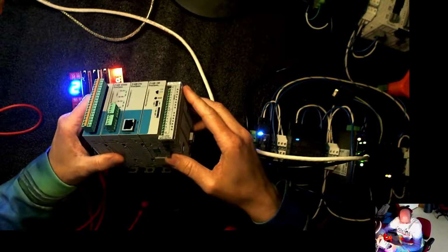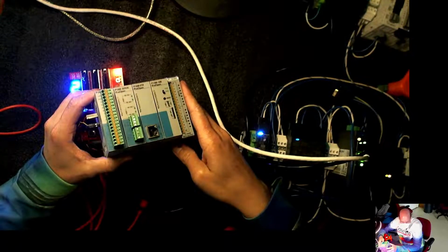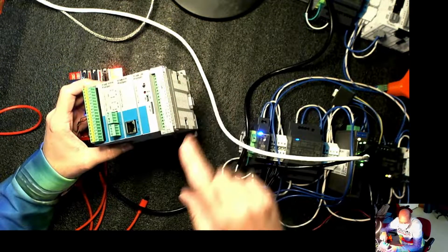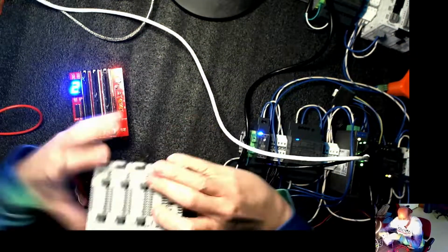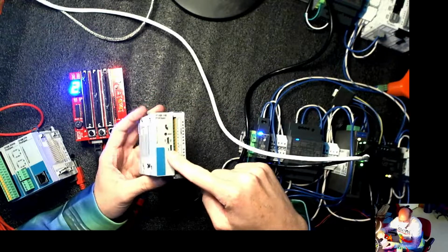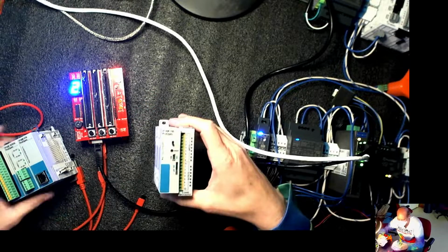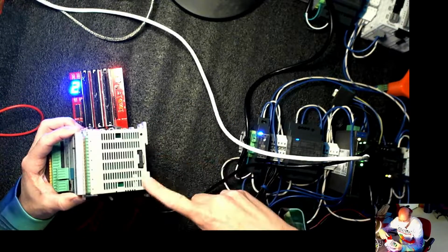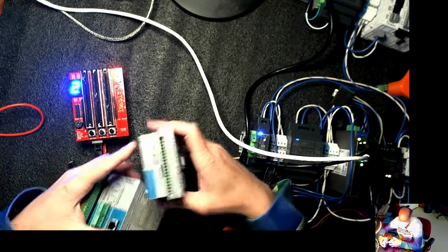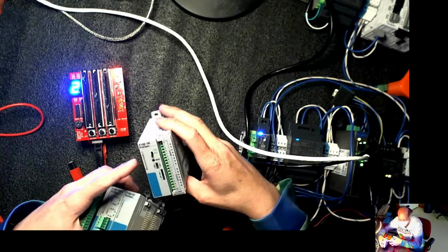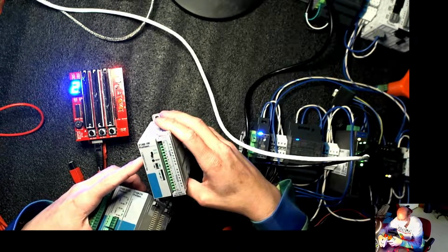This weird guy is a PLC with an Arduino for a CPU. So the CPU module here is a SAMD21 Cortex-M0 that you program from Arduino, not from the PLC IDE. And then there's shields that snap onto one side, and then PLC IOs that snap onto the other side. So this from Automation Direct is the P1AM100. They have a similar one that's Cortex-M4 that's slightly more expensive.